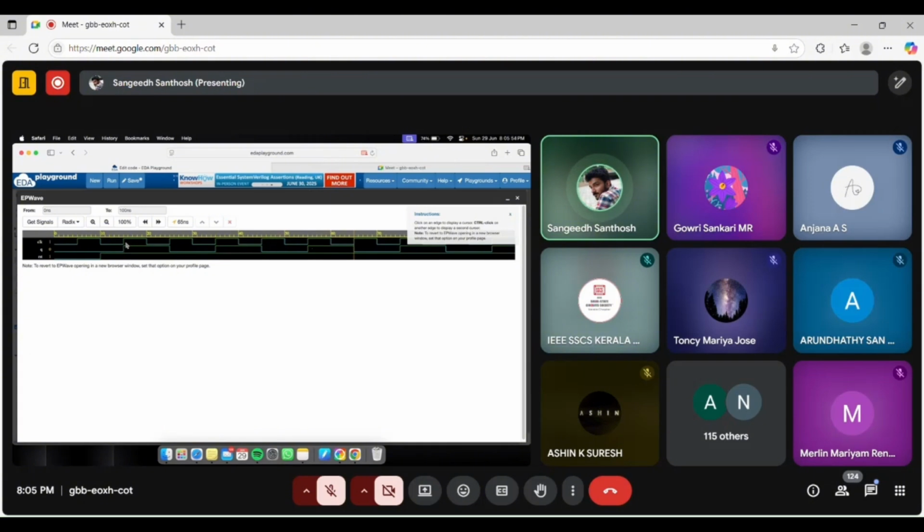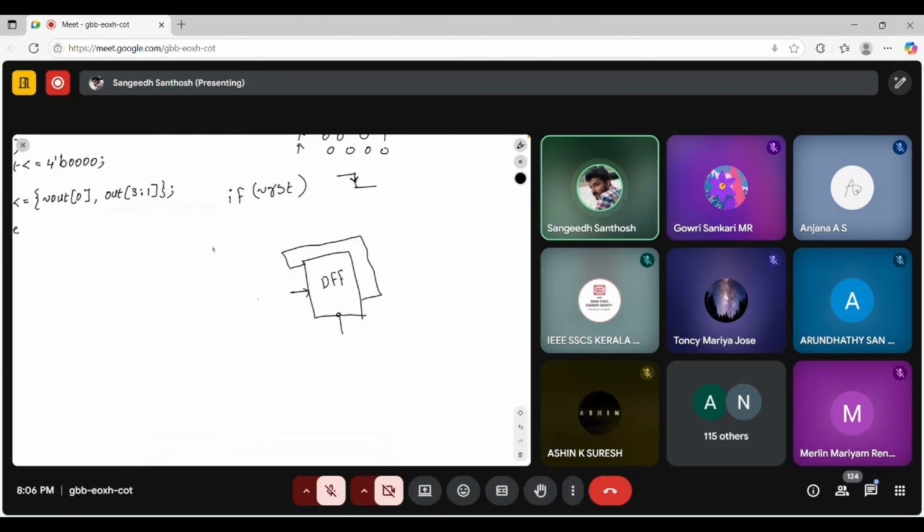As you can see here, whenever the reset is out, our output is becoming 1 for one entire clock cycle, right? So here the frequency is divided by 2. You are seeing this? Likewise, our Q is becoming 0 for an entire clock cycle. So if our clock is like this, our output will become like this.